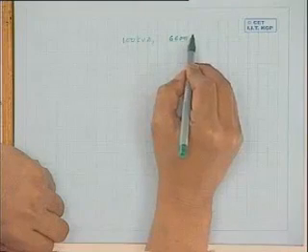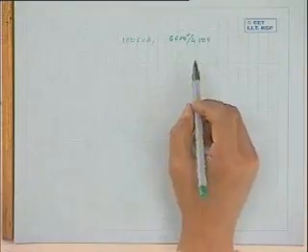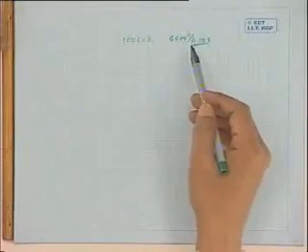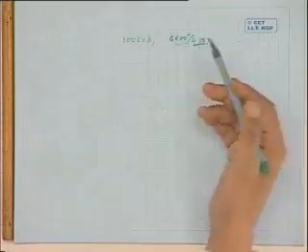I am telling only the lower side, and suppose its rating is 6600 volt by 400 volt transformer. In that case, if you want to do a load test on the transformer to ascertain the real life situation in the lab, then you require this sort of voltages to be present. At least 400 volt should be present. 6600 volt will be perhaps induced, and you have to connect a load whose capacity is 100 kVA. And all this you are doing just to test the transformer, and your power, whatever will be consumed, will be just wasted,